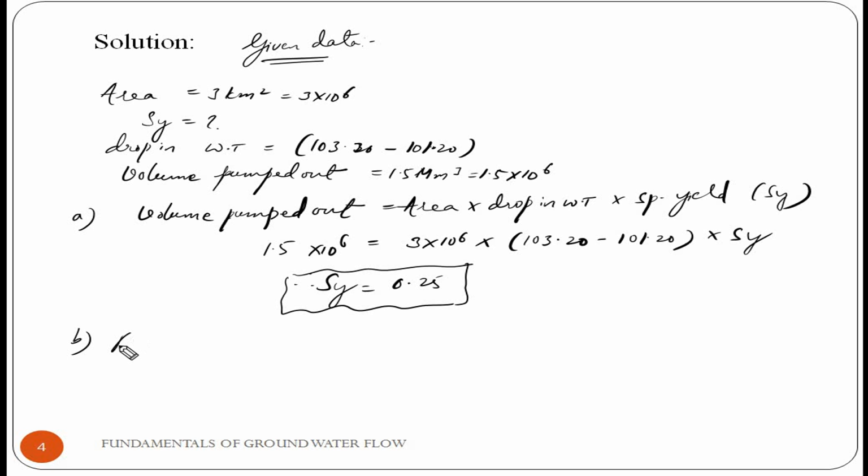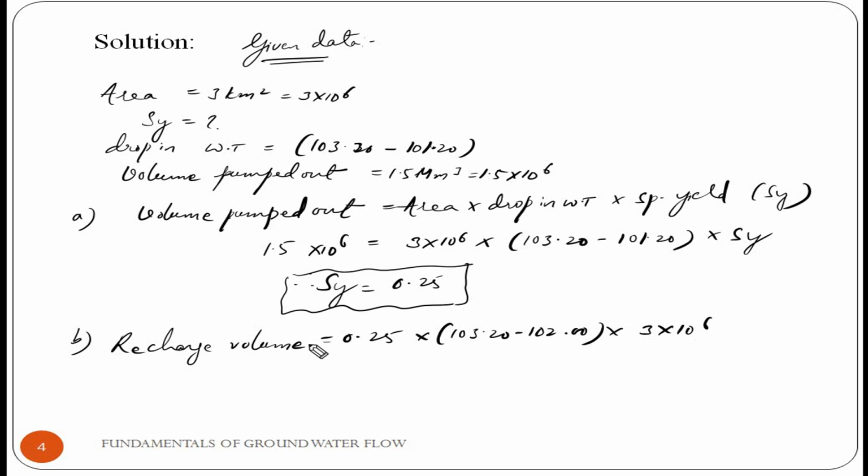So the second condition here, recharge volume is equal to 0.25 into (103.20 minus 102.00) into 3 into 10 to the power of 6. So the recharge volume is coming to around 0.9 million meter cube.